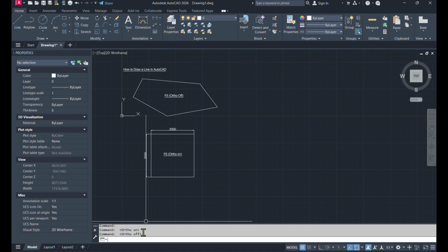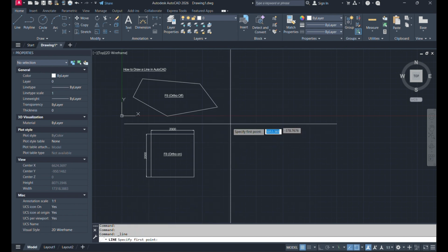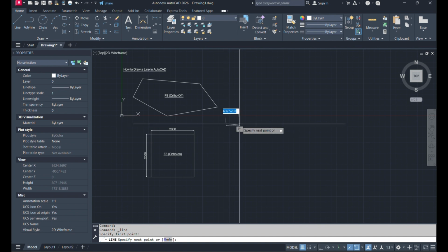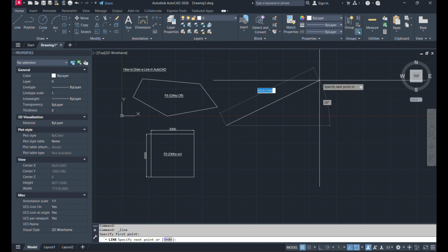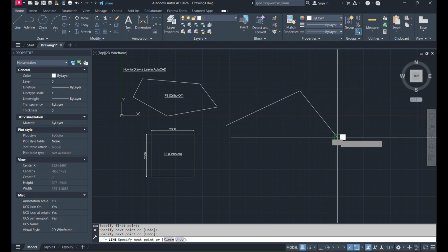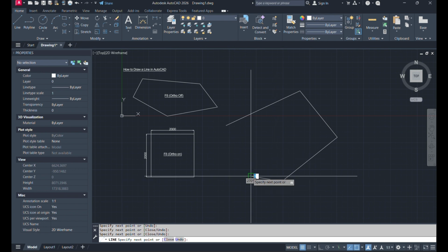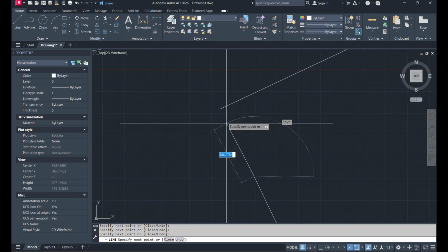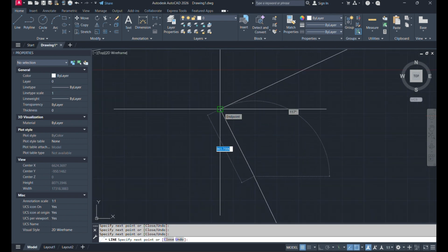Now you are free to draw lines in any direction. Okay, so click, see, I can draw at any angle. Click to specify the first point, and then move your mouse and click again for the next point. This is how we create the non-straight line. Then after that, you can connect to your first starting point. You can see the end point of the cursor. This is what we call the snapping point. Okay, you click this.